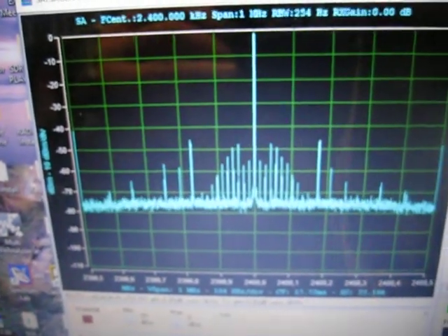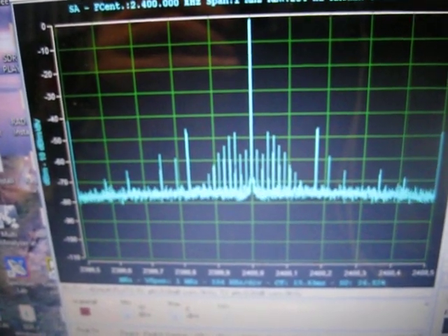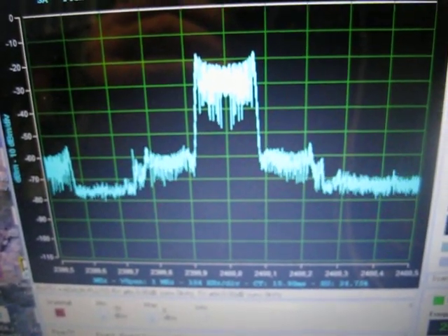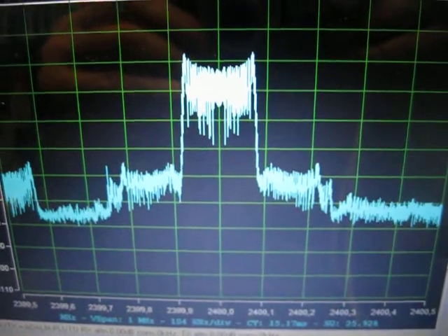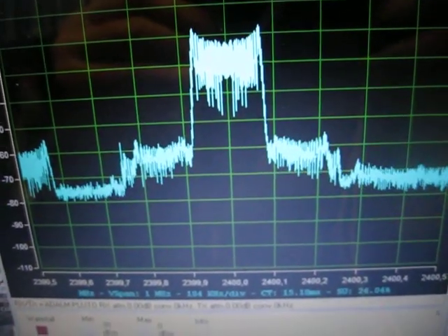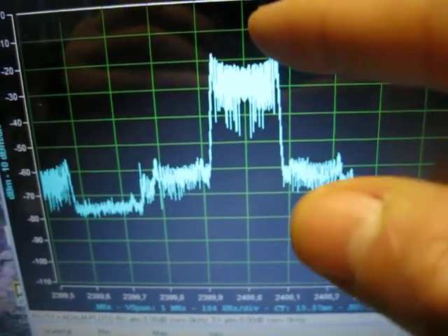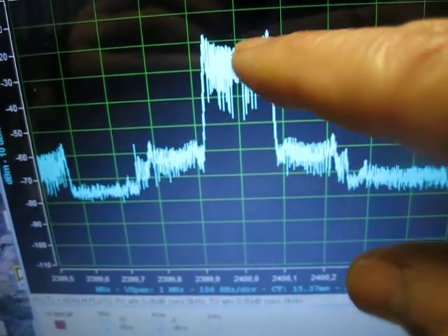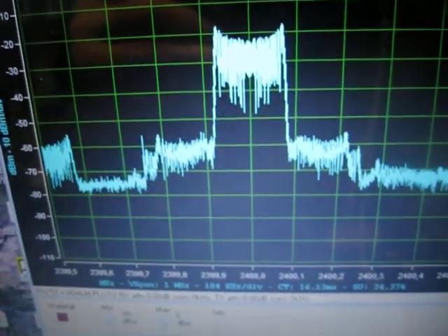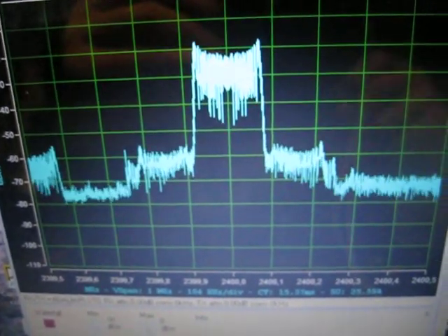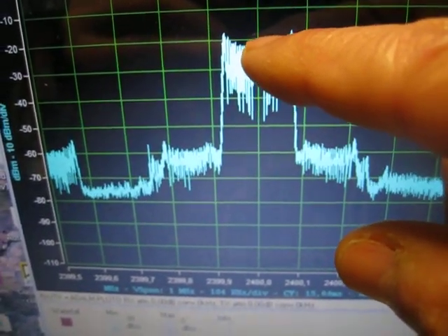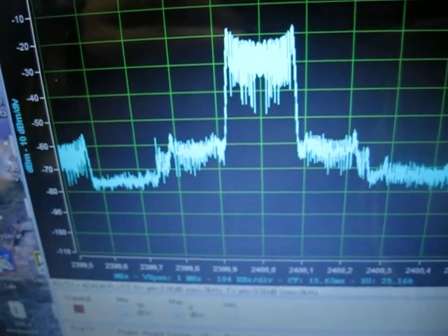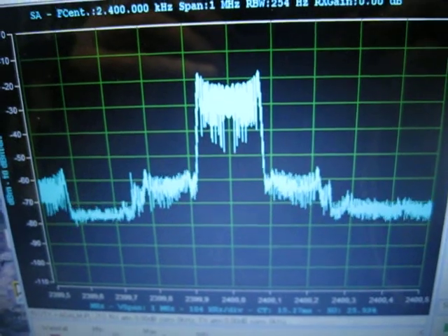and I know it modulates, but sorry, it was wrong. I put FM narrow, and now it is okay. It is wideband, and you see that there are also the spurious modulated, but let's say that the modulation is correct, because we have a total of 100 kilohertz per division, so it is 1.5 division, and so it is 150 kilohertz peak to peak.